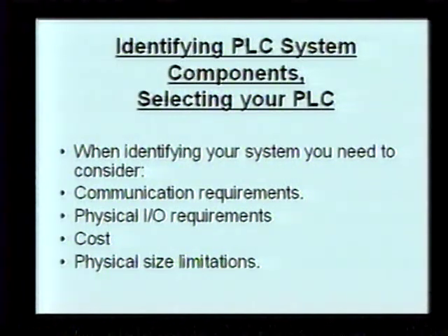So let's first talk about the communication requirements. Do you need to talk to any DCS, a distributed control system, or another computer? And if you do need to talk to that other system, what type of communication protocol do you need? Do you need a Modbus communication protocol? We're not really talking about this in this course, but it's important that you understand that there are different communication requirements, and it requires different hardware and different programming skills to satisfy these communication requirements.